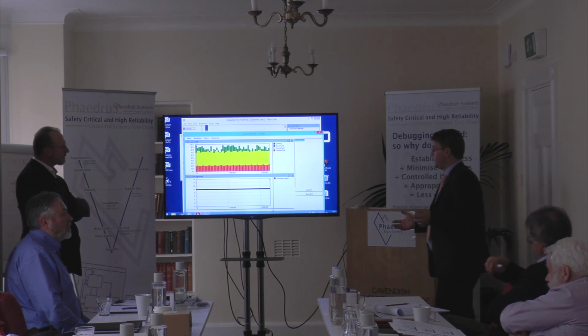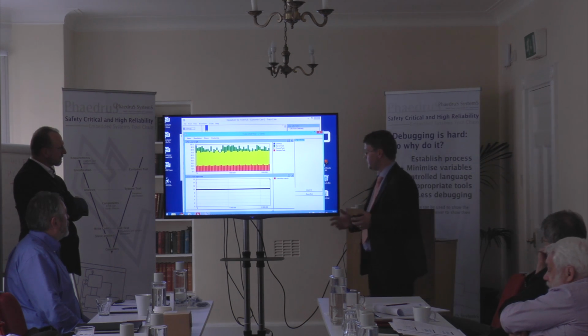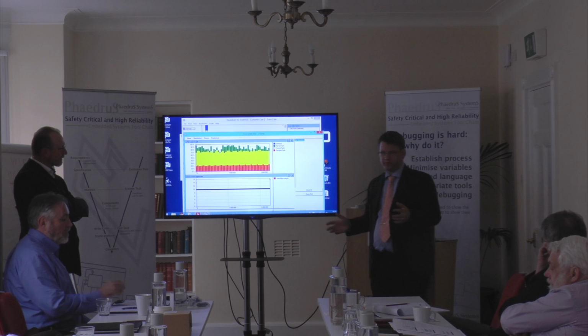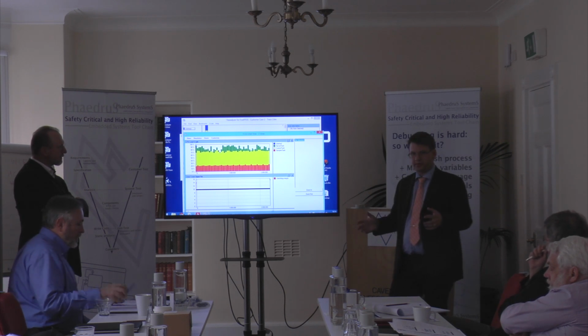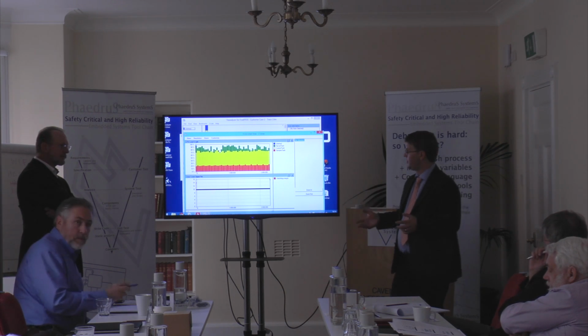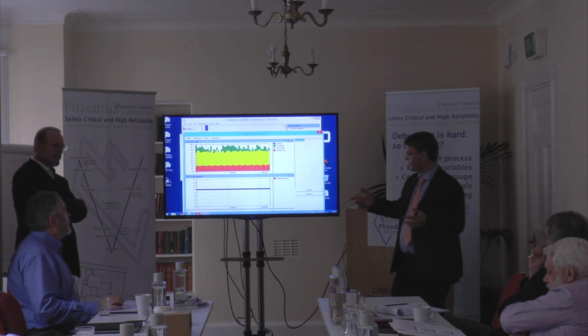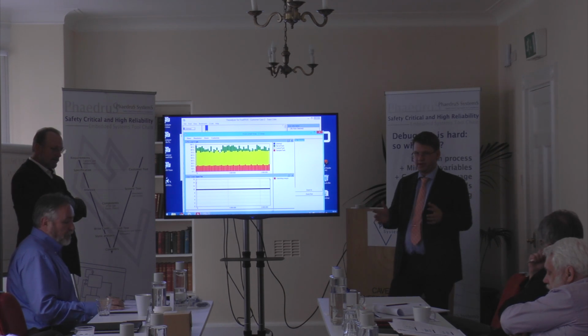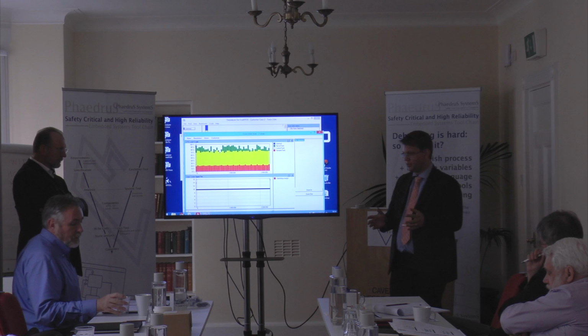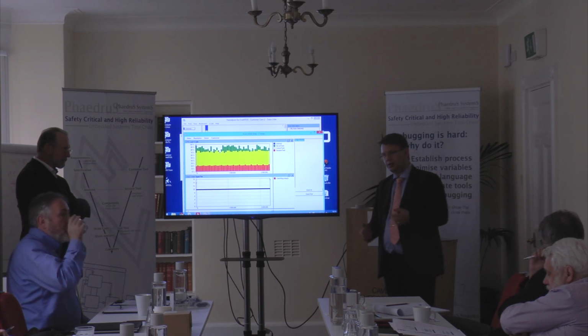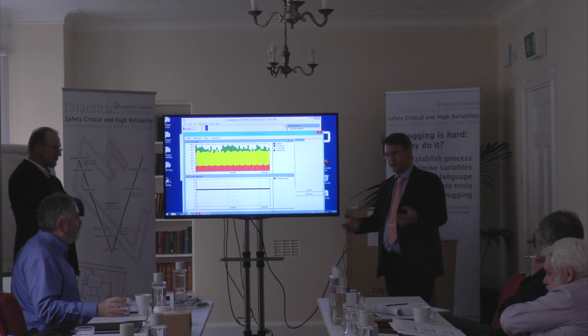And the great thing with the new Tracealyzer version 3.0 is that we have support for continuous streaming of trace on a standard JLink debugger. So instead of a few seconds of trace, limited by the amount of RAM in the chip, we can trace for many minutes or even hours and hours.